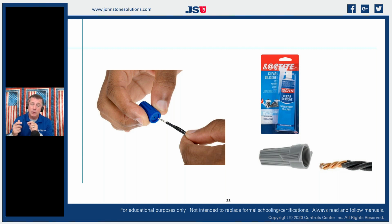And we're also putting those copper conductors inside of a spiral that is a dissimilar metal. So I will guarantee it has additional corrosion inside of that connection where we're twisting it together. So whether you're using a solid conductor or a stranded conductor, if it is a communicating system, you must cut off any existing wire nuts. You need to use either a waterproof or an underground style wire nut that has dielectric grease inside of it, or you can use a standard wire nut. We just need to make sure that we have clean copper that we're starting with.